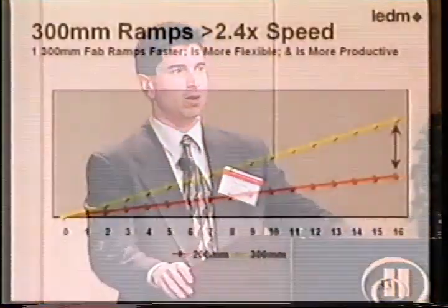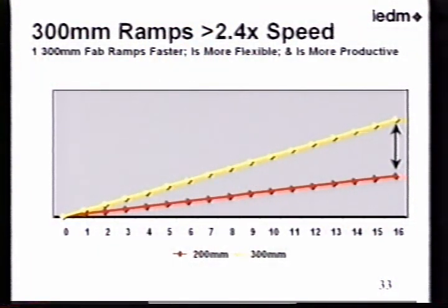And when you apply a 300 millimeter conversion on top of Moore's law, the conversion from 130 nanometer to 90 nanometers basically means that we are going to see more than a 4-fold improvement in terms of the transistors that we're going to put on a wafer. A 4-fold benefit that goes to our customers.